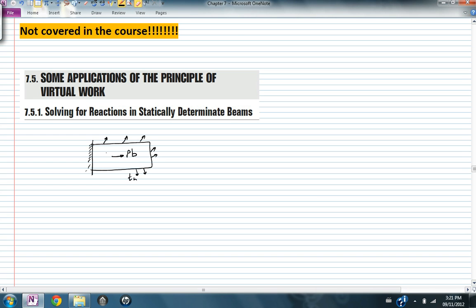and this continuum has a continuous stress distribution inside. At every point I know what the equilibrium stress is, the stress that satisfies the equilibrium equation. If this object is in equilibrium, and from that equilibrium I apply a displacement field u star, so every point will move with a displacement u star,